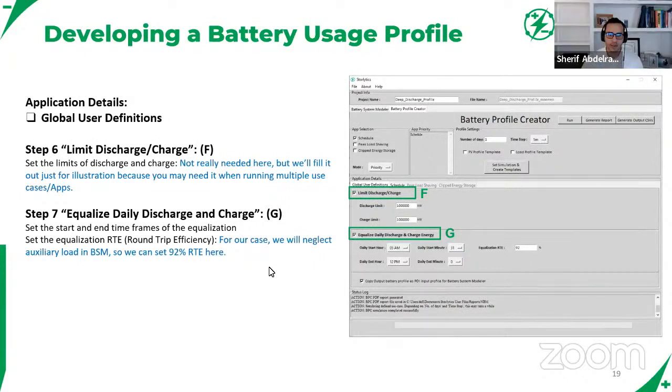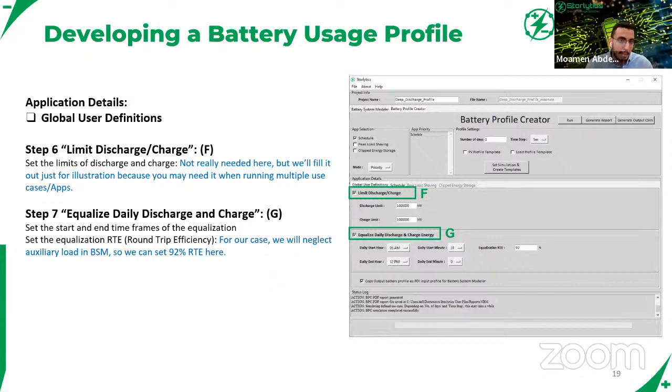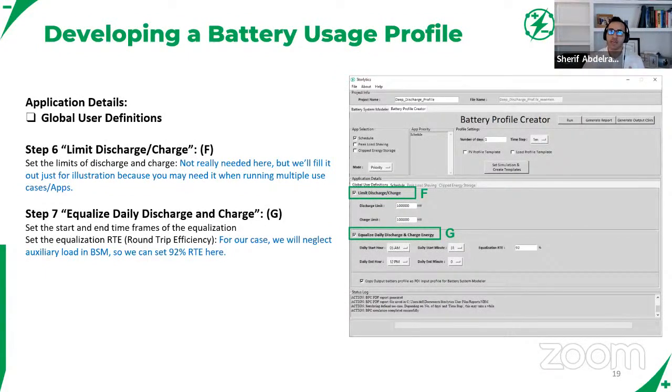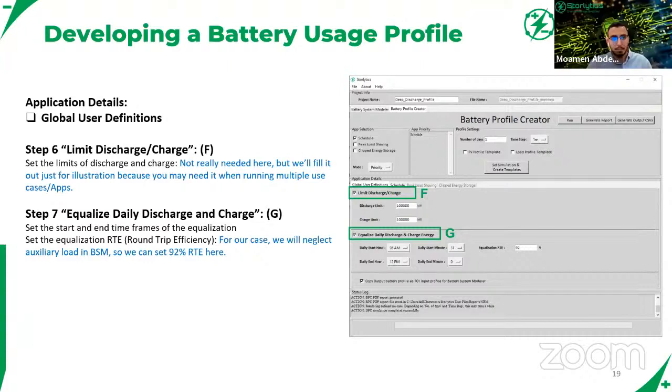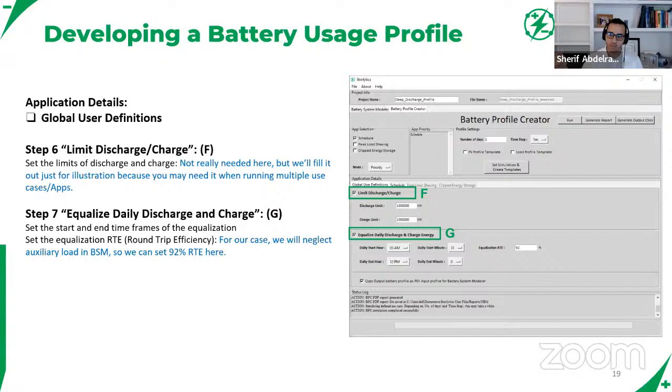Yeah, and I'll just add here, as you shift to running an actual simulation with an actual battery system defined, if you're not accounting for round trip efficiency, and if you're not energy neutral, or at least close to energy neutrality with a shift towards more charging, what you're going to find, if you have a multiple day simulation, is that day over day you're either adding on more charge or adding on more discharge.